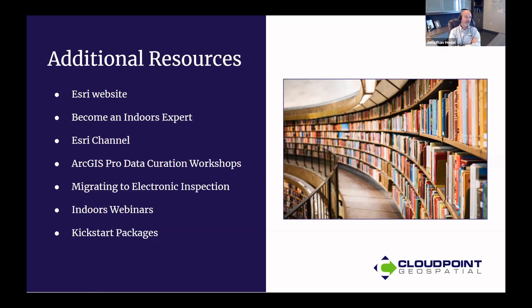That was the 3D camera we utilized, and we purchased the professional grade camera that's on a tripod. It's got a 134 megapixel camera on it, so it's obviously very high resolution. I would love to hear of somebody's experience. If you want to try out an iPad Pro, I'd love to see how that accuracy stacks up. But what we found with our camera was that the scan data was typically accurate within about an inch and a half for a typical room if you're measuring dimensions.